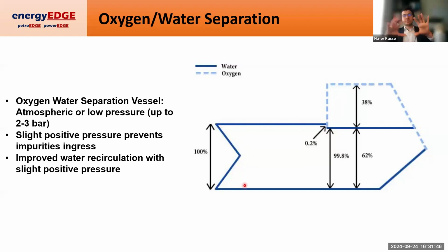So this is the water going into the stack, and I'm hoping that this helps with making it quite clear. 100 out of 100% of the water going into the stack versus, like we said, the 99.8% of the water that went in that also is coming out of the stack. So we have a reduction in the water of 0.2%, because this 0.2% of the water has been turned into hydrogen and into oxygen.